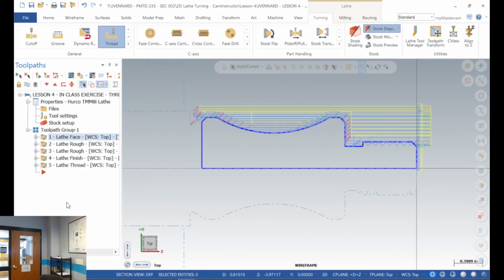All right. So like I was saying, I think I'm the biggest idiot when I do it. And I continuously tell students, hey, please don't do this in industry. Don't make a fool out of me. We've got a verify screen. I don't care what CAM software you're in, they've all got verify screens. If it's not verifying correctly, then I'm not taking it to that machine. I'm figuring out what's going on here.